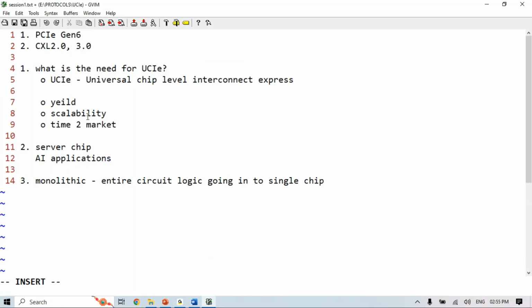For every different configuration, let's say I need different chips, one with 32 cores, another with 64 cores, I'll have to implement two different SoC flows, and do it as two separate design projects.